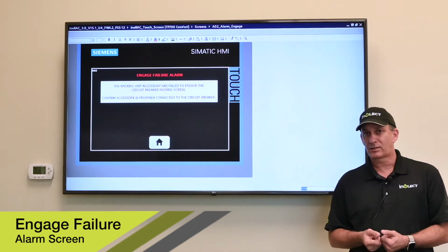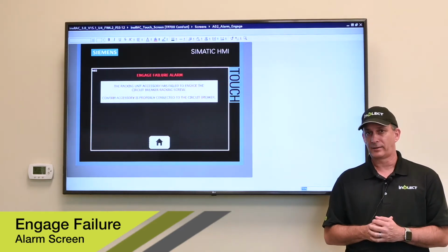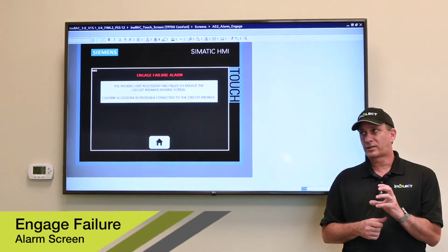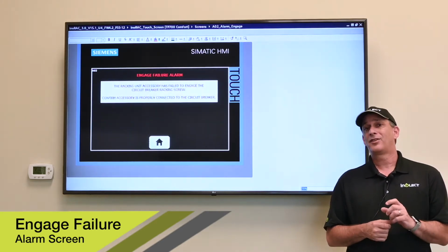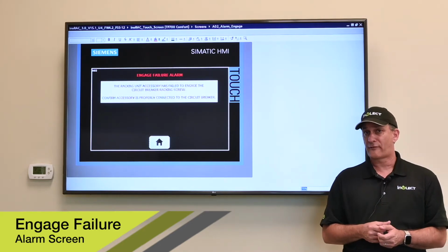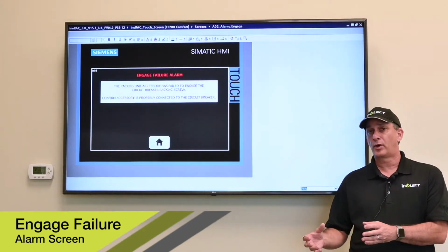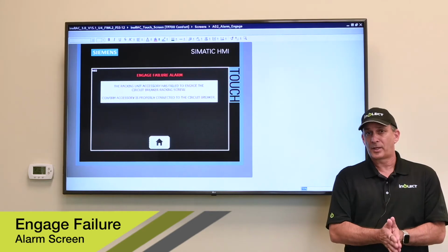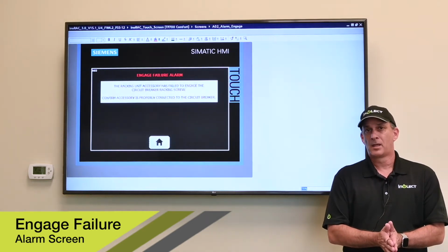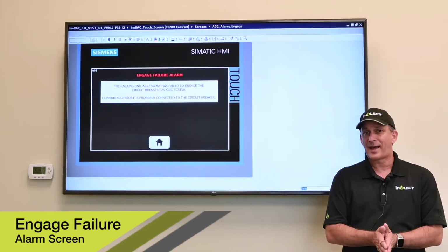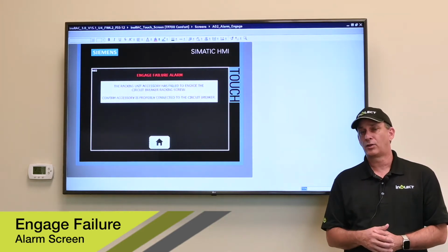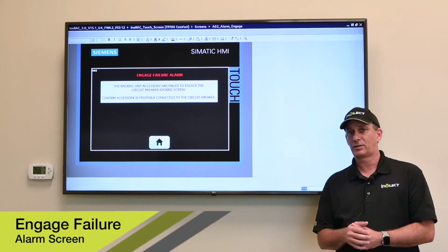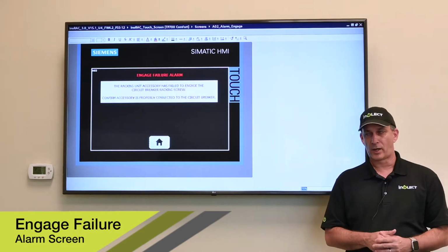You connect the system, you hit rack to connect. Well, the system is actually going to turn the racking motor in the counterclockwise direction at first to ensure that the breaker is all the way up against the disconnect position. And then once that permissive is satisfied, the unit will then pause and start racking the breaker into the connect position, or turning the motor clockwise.